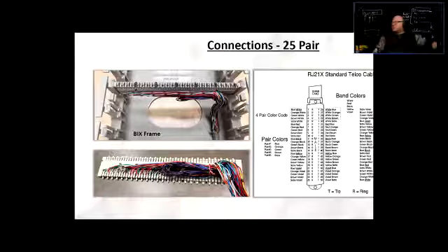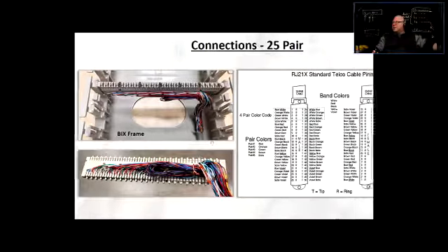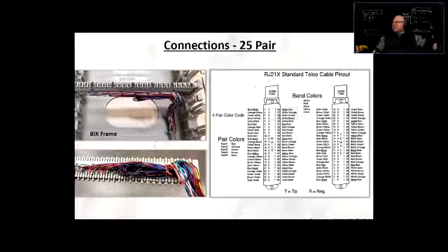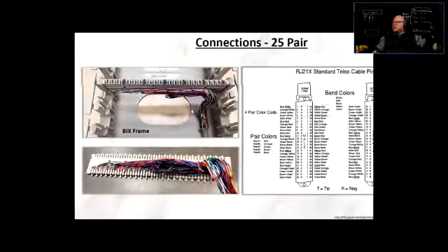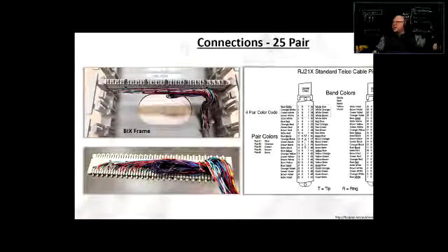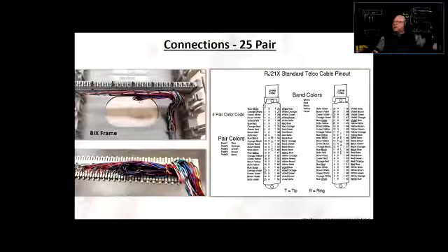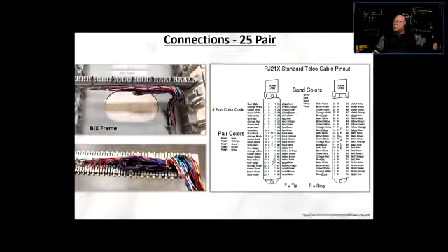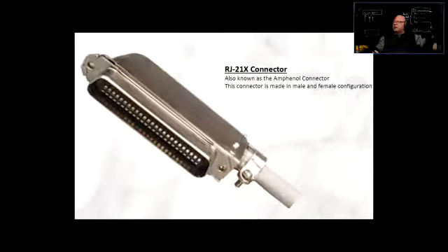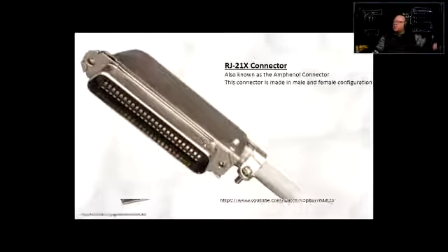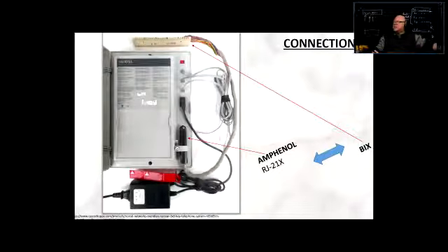All right. So we're going to connect one of those, and the other side of that is something called the RJ21X. One end of that cable is terminated on the big strip or whatever other termination strip, and the other end of the cable is terminated on something called an Amphenol jack. It looks like this, RJ21X. Sometimes it's called an Amphenol jack. These are pairs here, and they're being plugged in to the phone system like this, right?